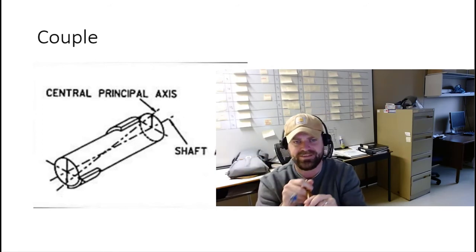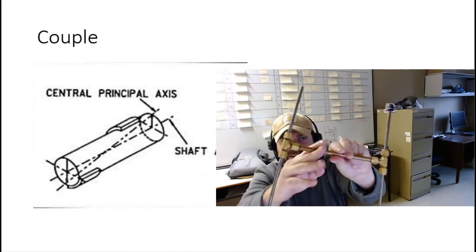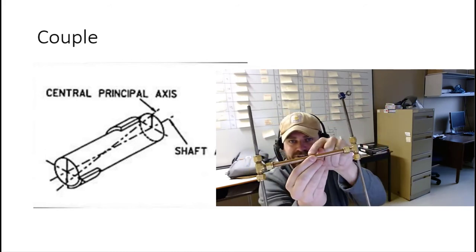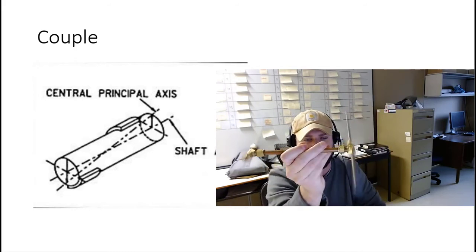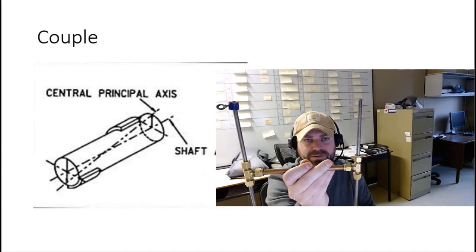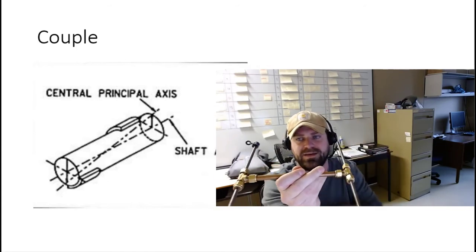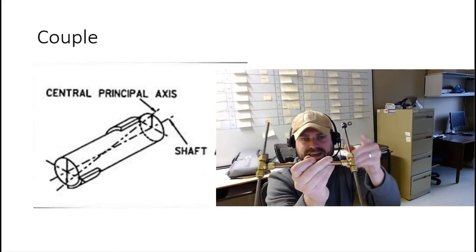Okay, so this is what a couple imbalance looks like. The centerline axis travels through the center but down on an angle this way, and it will just land wherever it wants to land, and I can't detect it at rest because it will just stay in any position.